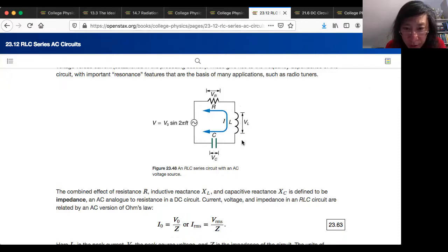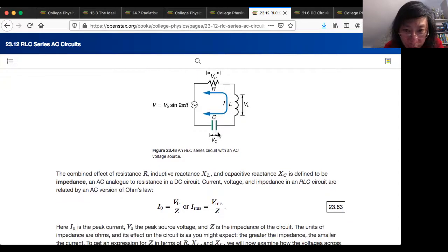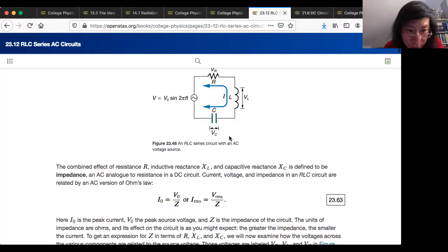And each one of these in series, right, uses some voltage, and that affects the current. Remember that in the end, your voltages all add up to zero, right? You've used them all up. Use some voltage here, some voltage here, some voltage here, and your current stays the same, right? It doesn't go to zero, it stays the same. But if you add up all these voltage drops, then they go to zero eventually, right?